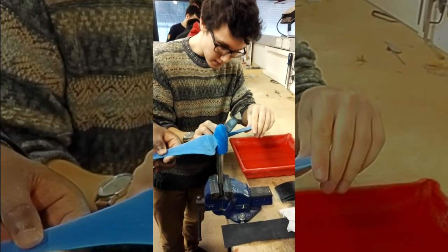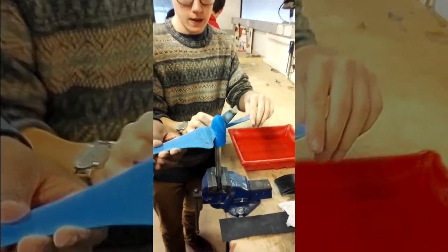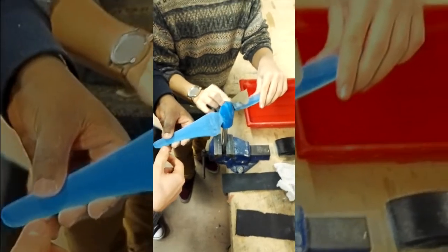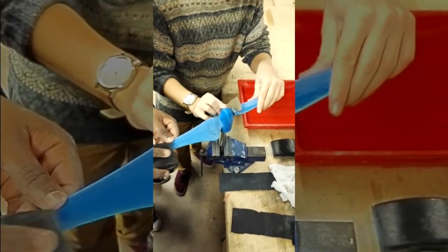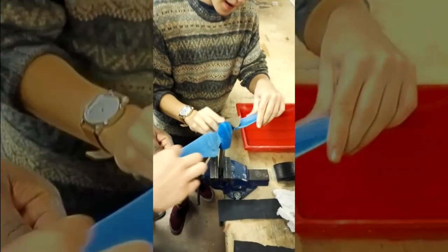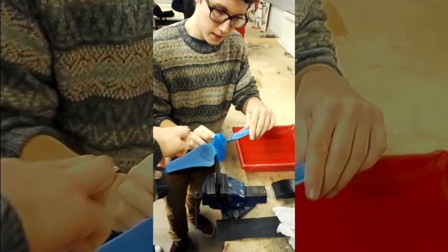The 2 blades and nose cone were manufactured using a 3D printer and were printed as one piece in ABS plastic. Due to printing limitations, the trailing edges were made artificially thicker. Therefore, the extra material was sanded off the turbine blade to match the shape we desired.